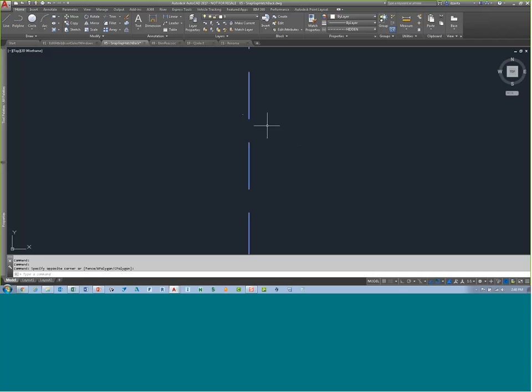That's a system variable that you can turn on and off. So if I type in LTGAPSELECTION, by default it's 1. If I set it to 0 and hit enter, and try to do the window crossing again in between the gaps, it will not pick that data. It cannot see that data. But if you touch the actual entity, it'll select it.